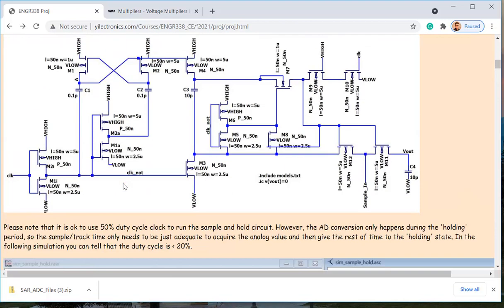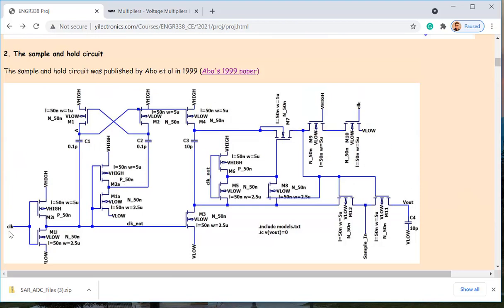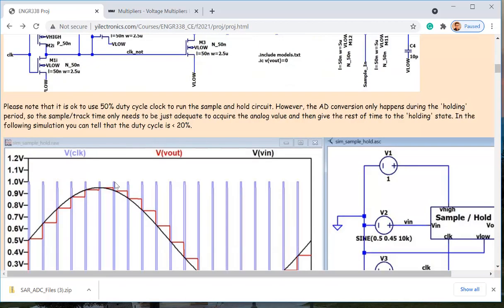A quick question. When you want to make that type of clock with an ADC chip that you have never used, for example, I give you an IC chip, right? It has a clock pin over there. And you can connect it to the Arduino's clock pin, so it's actually giving oscillation to it. But that clock pin won't be like something like this, right? It's not customizable. It's going to be a 50% duty cycle. How does that work?